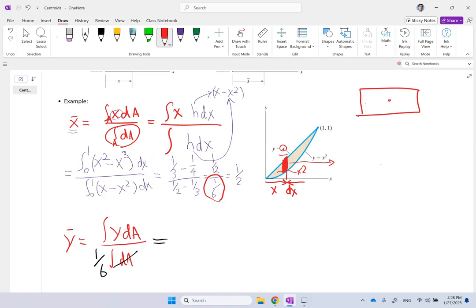You can show that, and we're going to talk about the objects that have symmetry lines. Any object, that's one of the easy things that you can talk about centroid. Any object that has any axis of symmetry, the centroid should fall onto the axis of symmetry. So if you have two axes of symmetry, then clearly the centroid will exactly be at their intersection.